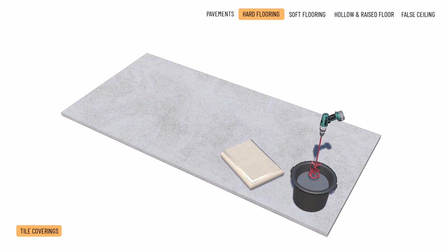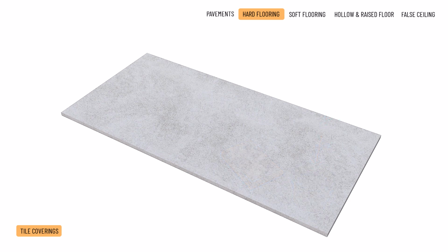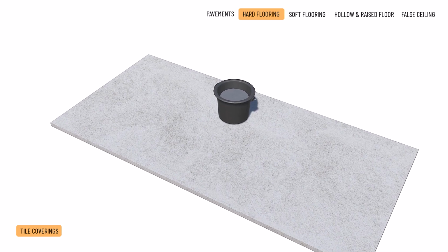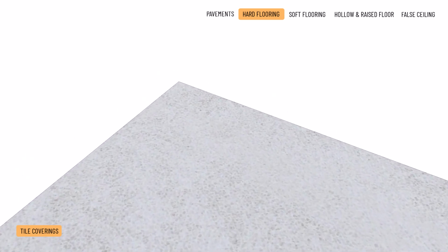Nowadays, tiles are no longer installed using the traditional mortar bed method. Instead, they are fixed using thin bed adhesive bonding. Practically, this means a 2 to 4 millimetre thick cement bonded layer of adhesive is spread beneath the tiles.